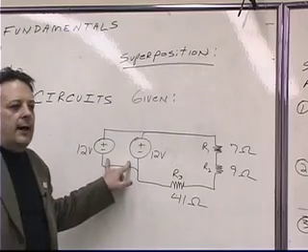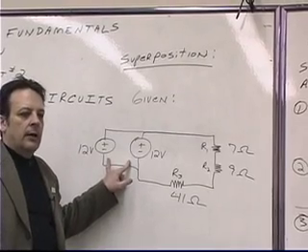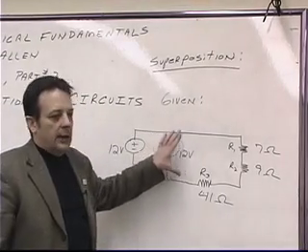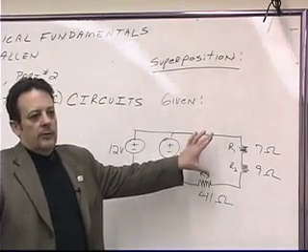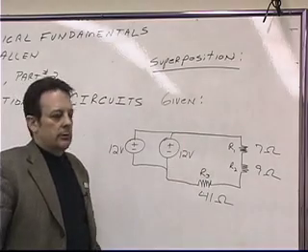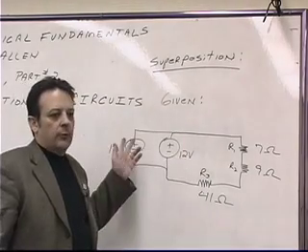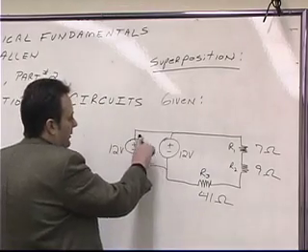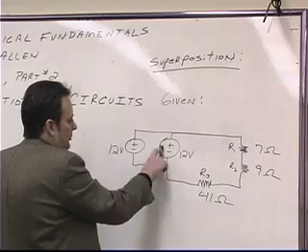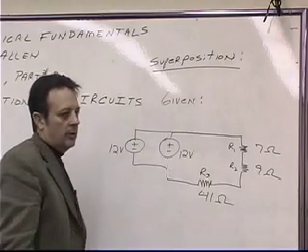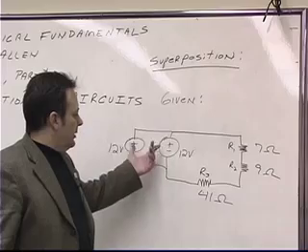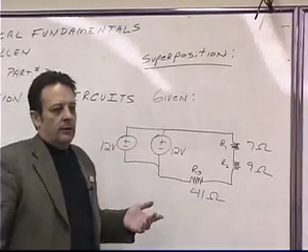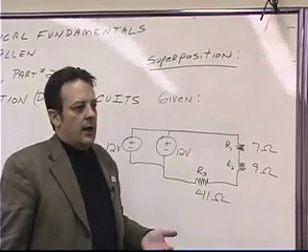Okay, when we have 2 batteries that are connected in parallel and they're both rated at the same voltage, what voltage do we get out of that parallel connection? Same voltage. Do we get 12 volts or 24? 12, right. Because Kirchhoff's voltage law says that the sum of the voltage drops around the closed loop has to be 0, which means that because of the way these polarities are situated, the voltages are not additive or subtractive.